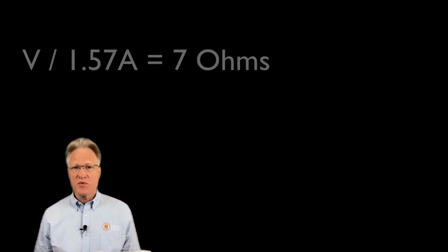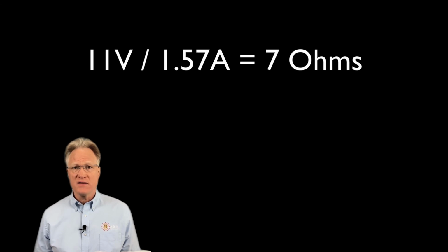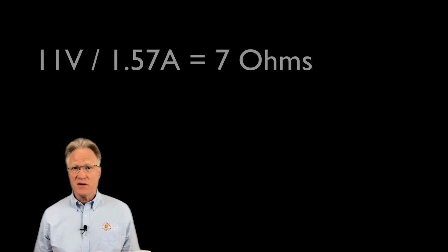The maximum resistance of the entire length of the cable must not exceed this voltage drop divided by the maximum current draw of the ONT, or 11 volts divided by 1.57 amps, or 7 ohms. That's 3½ ohms one way.